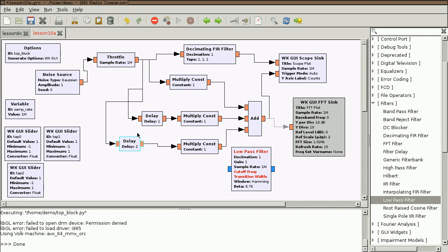So there are only 3 output samples that can be affected by any one input sample. Those 3 output samples happen, and then it's over. There's no additional, long-term effect of any input sample beyond those 3 output samples. So since it's only 3, that's a finite number. We call it a finite impulse response.